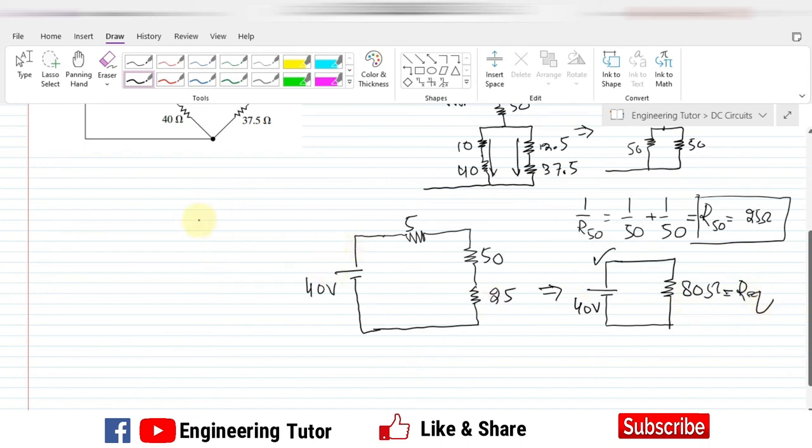So now here we can easily find out the value of current which is flowing or provided by the 40 volt source. So that is basically, we can find it out by using the Ohm's law. So I is equal to V by R. V is 40 divided by 80, so it is now 0.5 amperes. Okay, so this is the current which is provided by the source.